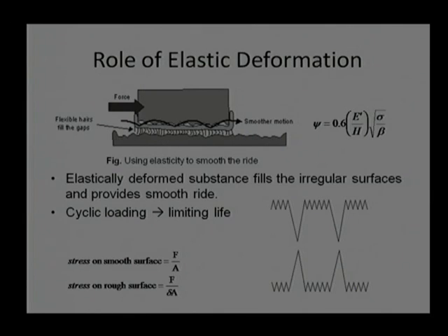However, there is a limitation. We know from the fatigue point of view, if any component is elastically deformed again and again, it will experience cyclic loading, it will experience fatigue. And if the stress is more than the endurance strength, the component will have a limited life. We know other than iron or ferrous material, no component has any endurance strength.